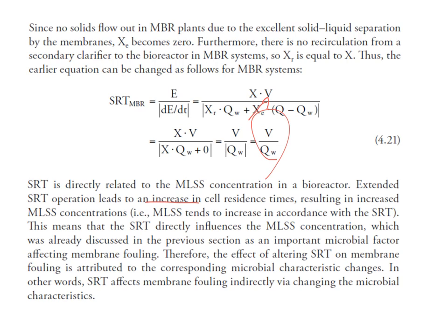This means that the SRT directly influences MLSS concentration, which was already discussed in the previous sections as an important factor affecting membrane fouling. So again, SRT affects MLSS. Of course, it affects other conditions, but one of the ways that the SRT affects membrane fouling is that SRT affects MLSS and MLSS affects fouling.